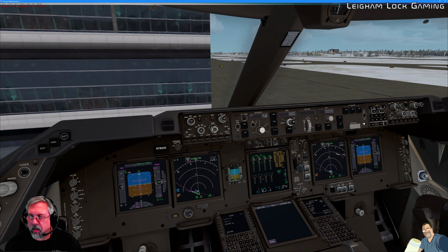The autopilot disengage bar is in the up position. And the heading for our runway today, if you recall, we can actually get that right from the legs page. 301 degrees, so that makes sense. We're on runway 30 for departure. So we want to dial in a heading to match the heading of the runway. 301.